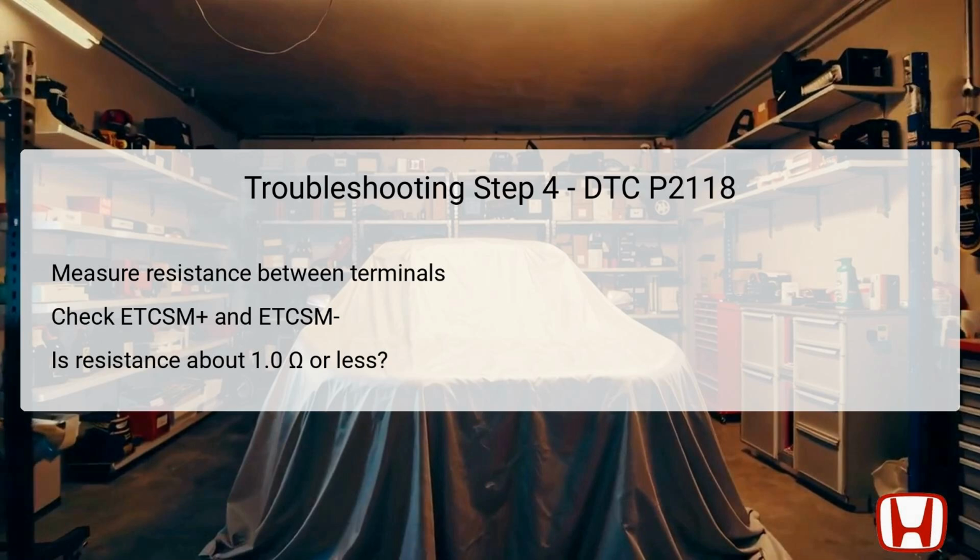If the measured resistance is within this acceptable range, it suggests that the wiring is functioning properly, allowing you to proceed with further diagnostics. Conversely, higher resistance readings necessitate addressing wiring problems before moving forward.